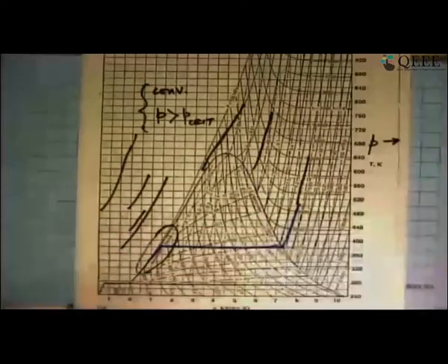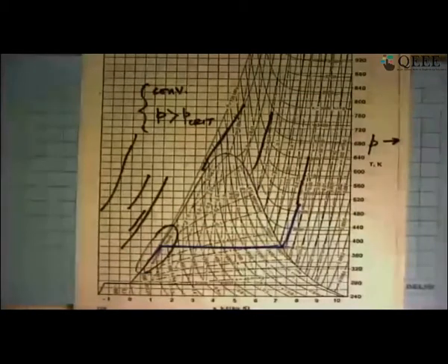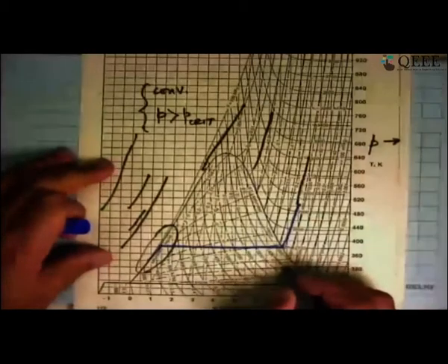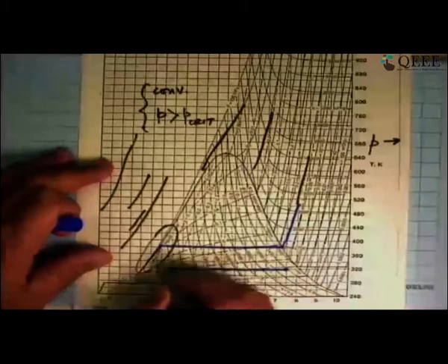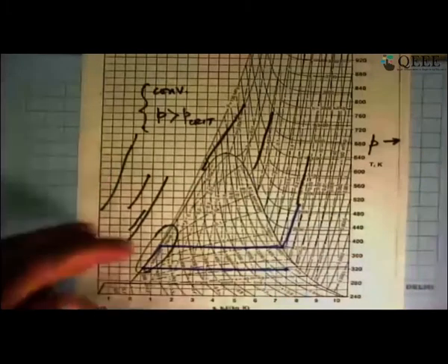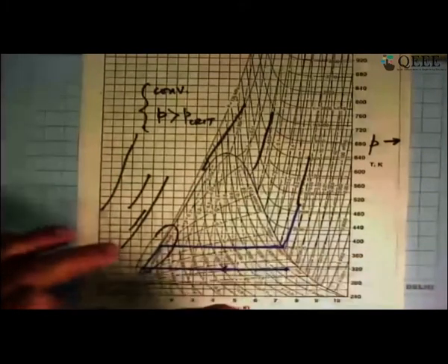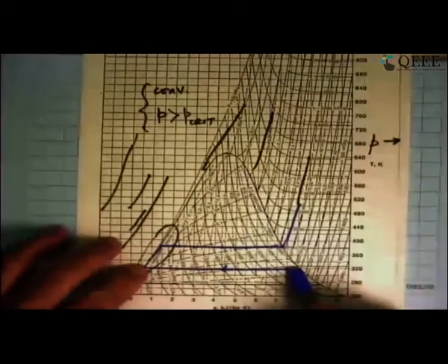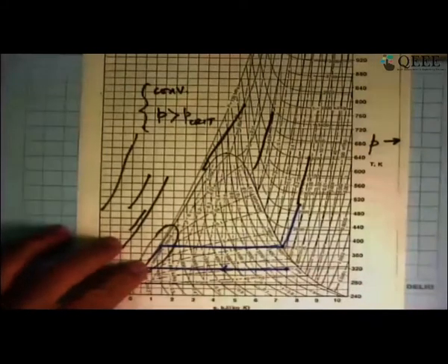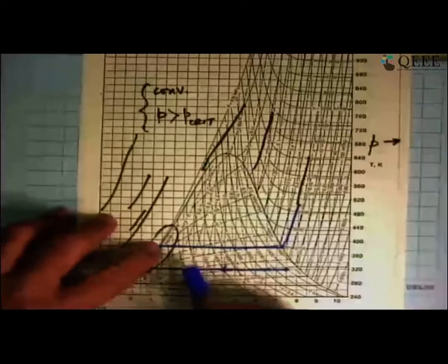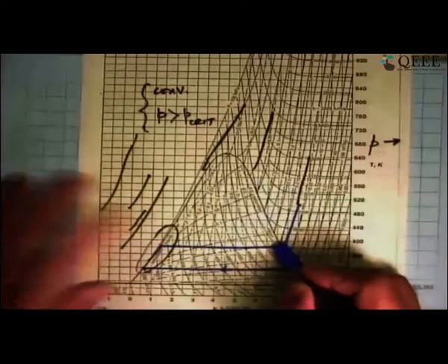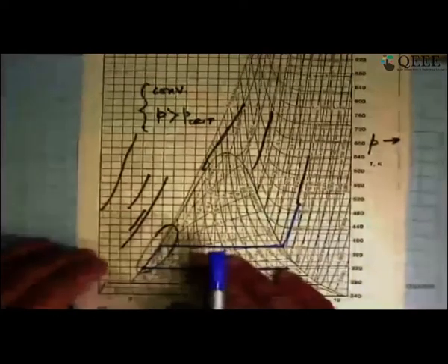If it is a condenser, then it could be slightly different in that the exhaust steam could be already a wet steam, and our objective is to just condense it and bring it back to a saturated liquid state. And this only means that you need to design one thing for the condensation of the vapor. So the condensation part we will look at tomorrow. Today we'll look at how we get a saturated liquid to become a saturated vapor, and that is called boiling.